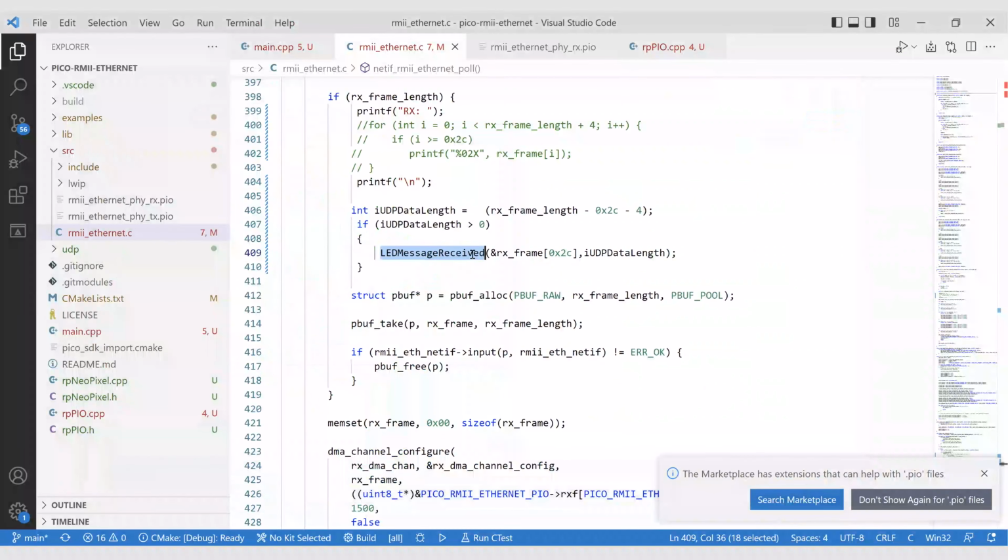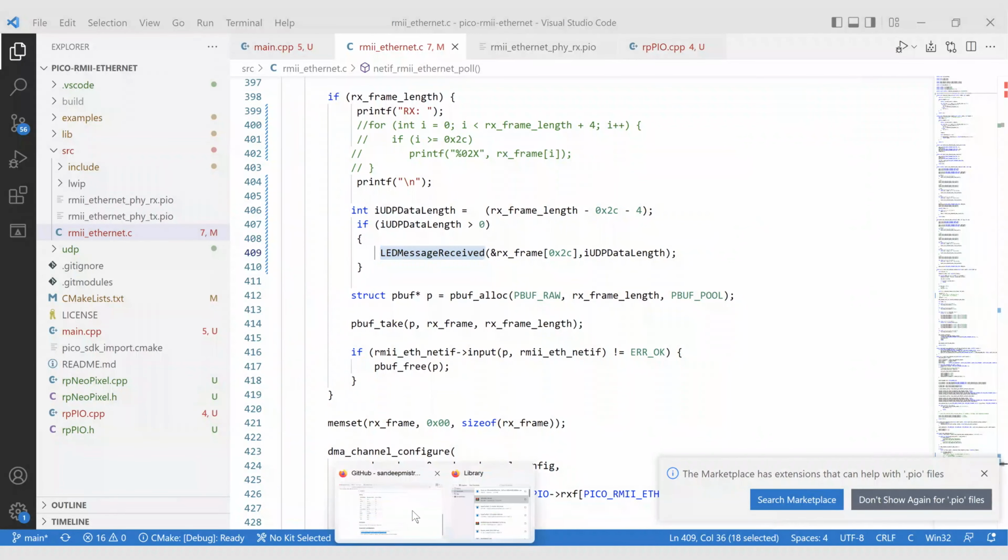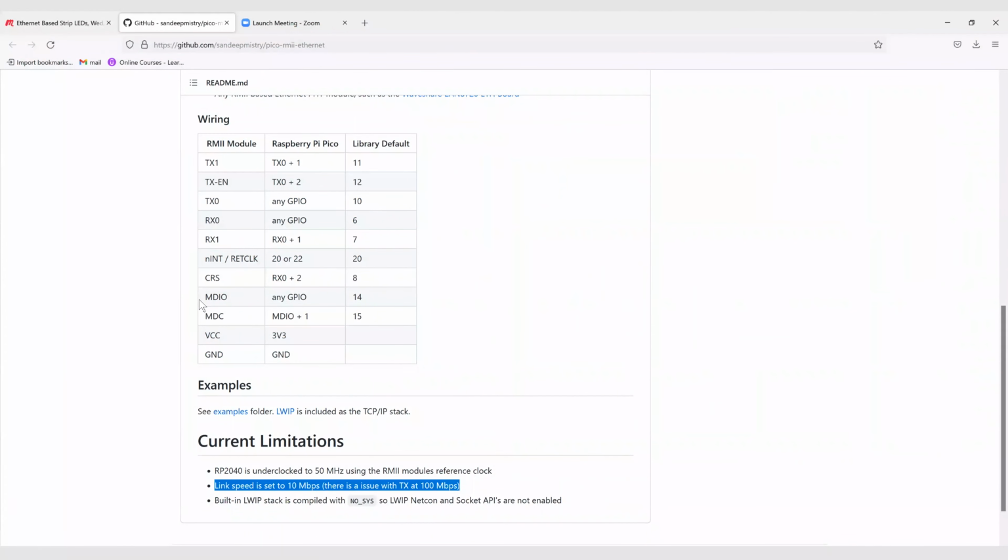Other things to mention, so a key part of the Ethernet interface is the setup interface, MDIO. So there's this two-wire communication with the PHY. The PHY itself has registers where you can read and write them, and that's how you configure the PHY for different things. So in the code, there are functions which I have not looked at